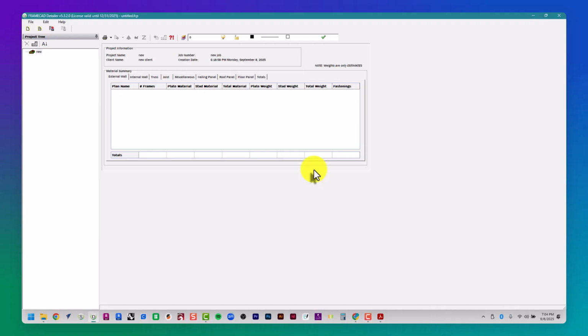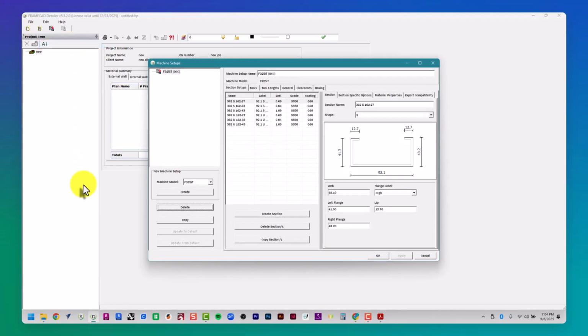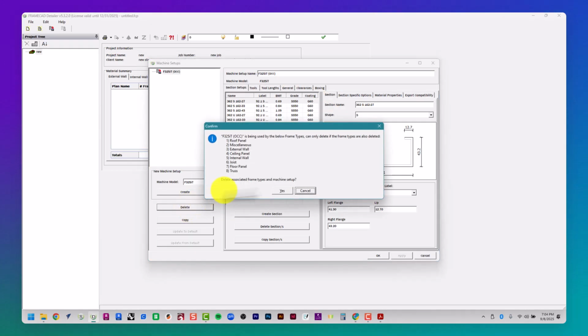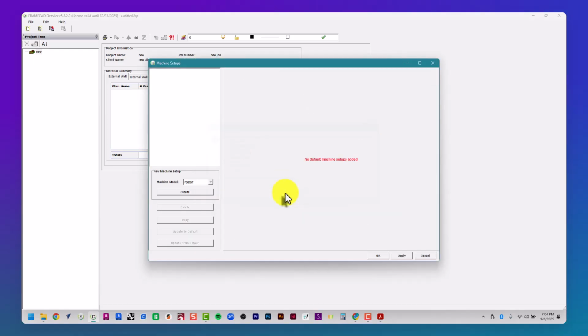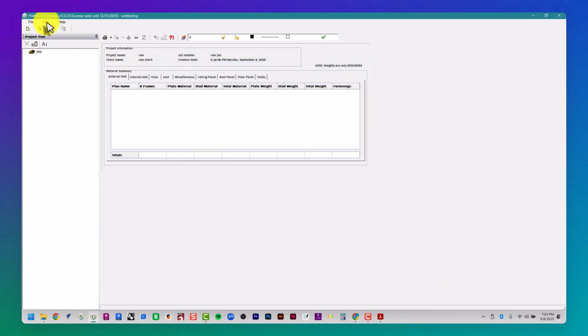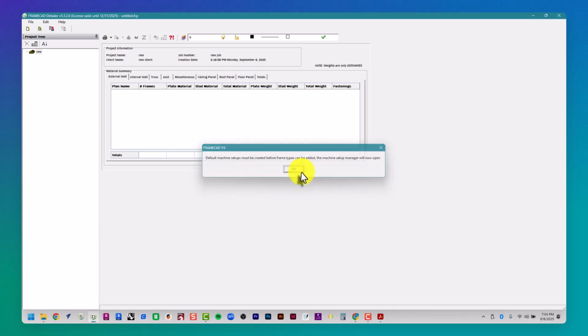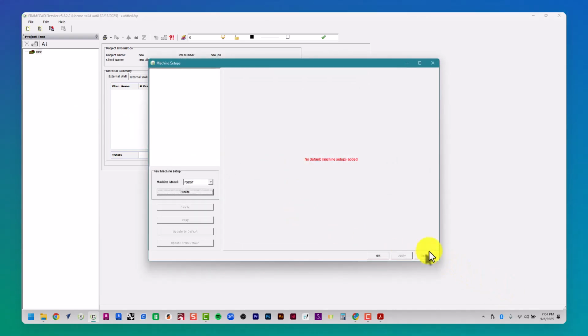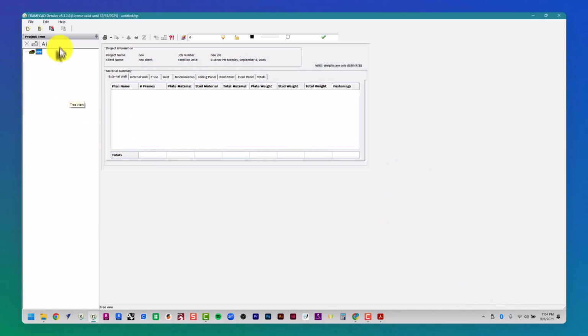So now, if I wanted to import all that, File, Import, Frame Types, Machine Setup, Steel Setups. Here is where I saved it. Actually, this is not where I saved it. Let's go FrameCAD. Let's go to Workshop, Machine Setup. All right, here it is. 250908 OCC FrameCAD Machine Setup.sups. Okay, I'm going to bring that in.